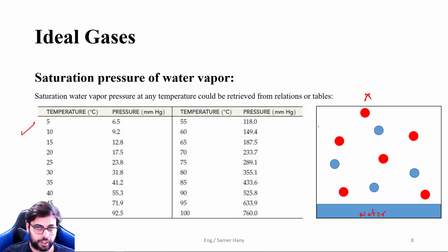It will always be, given the proper amount of time, saturated with the vapors of that liquid, because that liquid still has some energy to vaporize some of the liquid inside of it. How much? Just retrieve the temperature and pressure from the table.